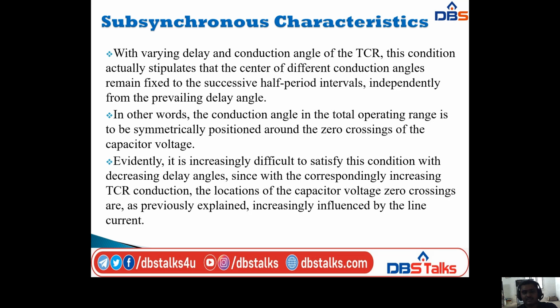So evidently, it is increasingly difficult to satisfy this condition with decreasing delay angles, since with the correspondingly increasing TCR conduction, the locations of the capacitor voltage zero crossings, as previously explained for the TSSC and TCSC conditions, are increasingly influenced by the line current.